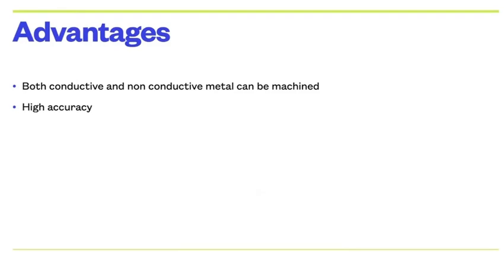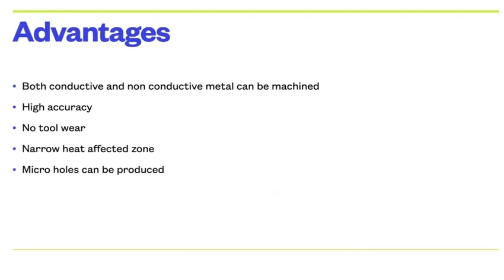Advantages of laser beam machining. Both conductive and non-conductive materials can be cut. It gives high accuracy, almost no tool wear. It has a narrow heat affected zone. Microholes can be produced. Hard and abrasive materials can be cut.